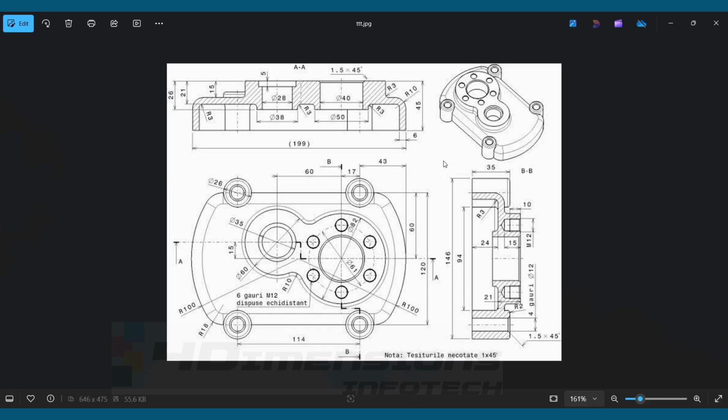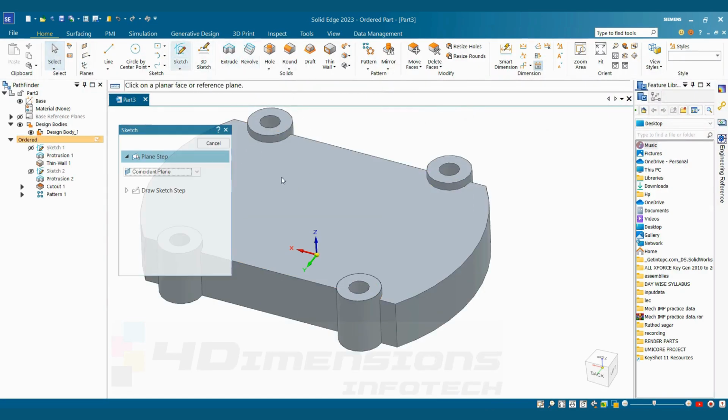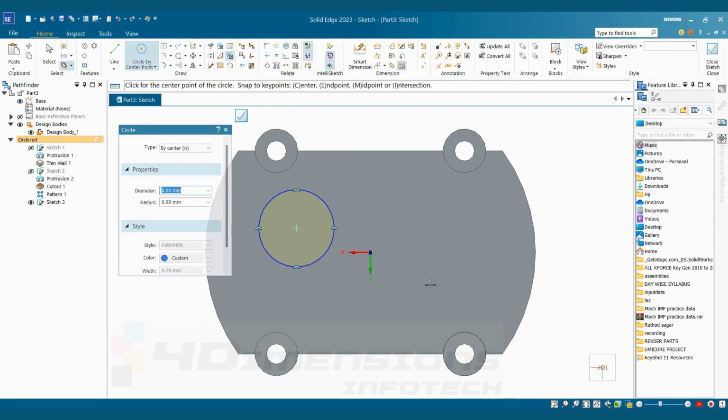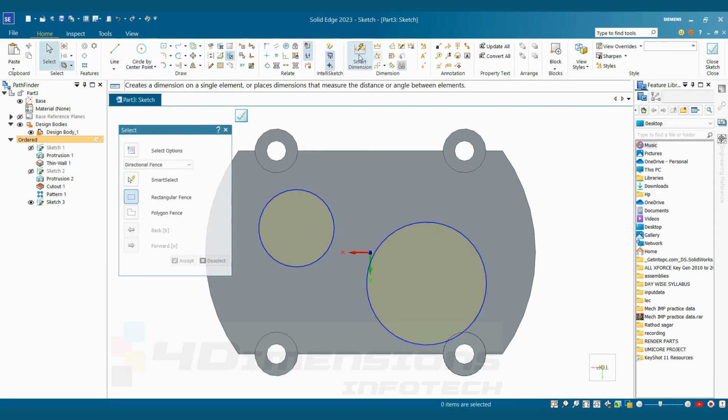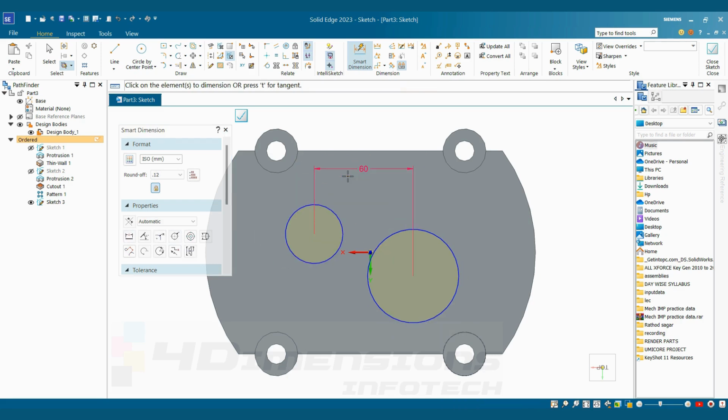First we are going to make all the extrusions here, then we are going to go for cuts and then modification commands. So now the next extrusion we are going to make is this digit. For that I am going to say sketch on this face. Select the face. We'll go with the circles here. There are two circles. Now the horizontal distance from center to center is given as 60 mm and the vertical distance here is given as 15 mm. The diameters given are 60 here and this is 82.